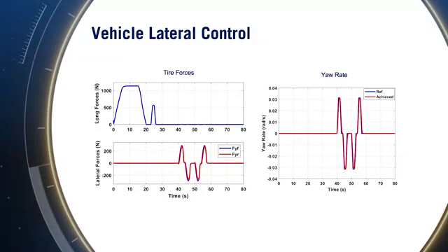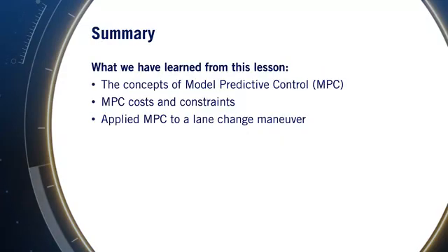MPC shows a lot of promise as a control technique for autonomous driving and can be used without modification for a wide range of operating conditions and a large variety of scenarios. This flexibility and convenience comes at the cost of increased computational requirements and relies on the availability of robust optimization solvers to always return feasible solutions in the available time window.